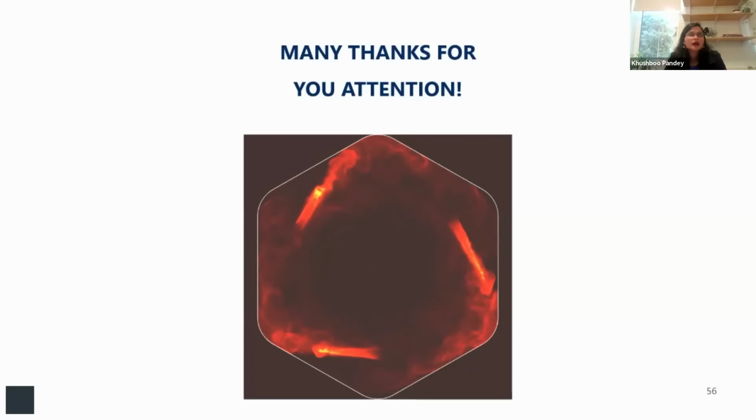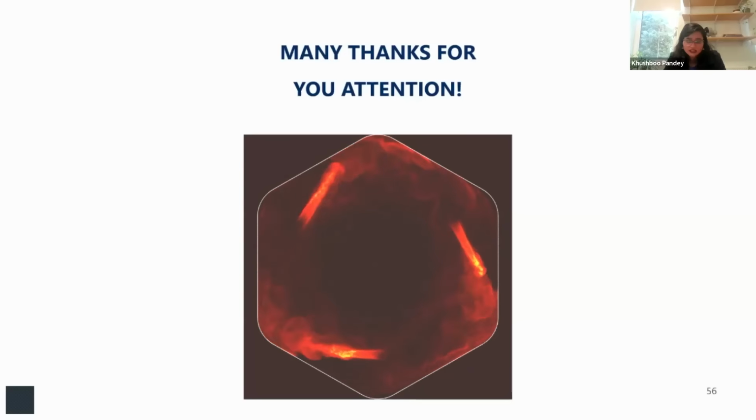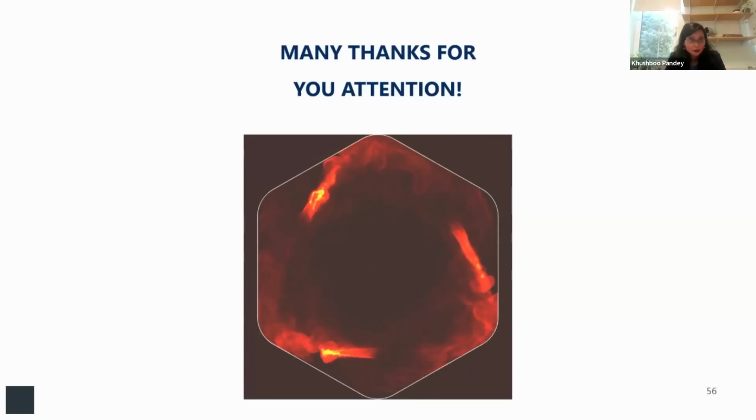Yeah, so for the spray and cross flow, or the leaf itself with the topology, the parameters were spray itself and jet to cross flow momentum ratio. So if we inject hydrogen at low power, of course, this essentially does not change any of those two, but it changes the temperature field around the sprays. That affects it, and that's how we can stabilize it, because it is giving that hot environment for the spray to be evaporated. So that is a good thought process, essentially.